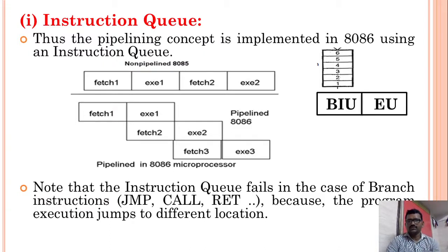Nowadays microprocessors are designed with a branch prediction logic circuit, and with that circuit the time will be reduced. Not for all cases. If after execution of a branch instruction the address obtained is the same as predicted, then the time will be reduced.